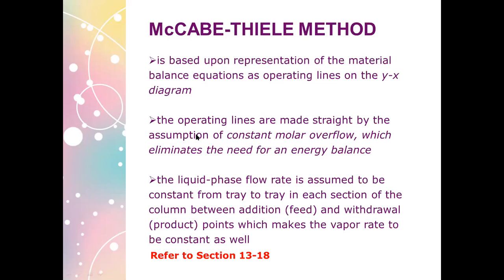The operating lines are made straight by the assumption of constant molal overflow, which eliminates the need for an energy balance. Since we assume constant molal overflow, we have operating lines, meaning they are straight.